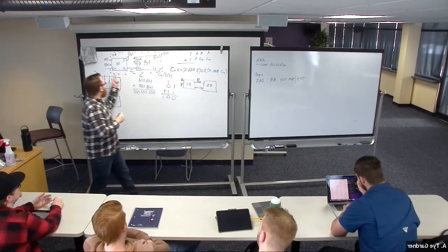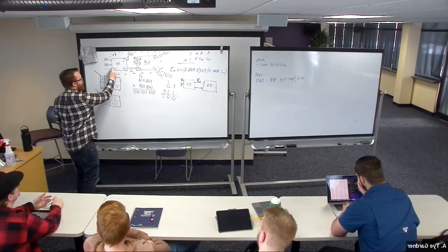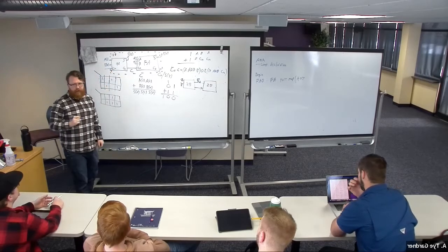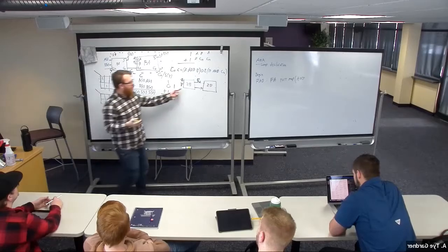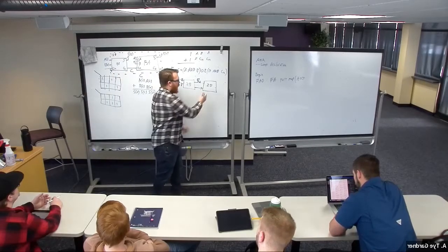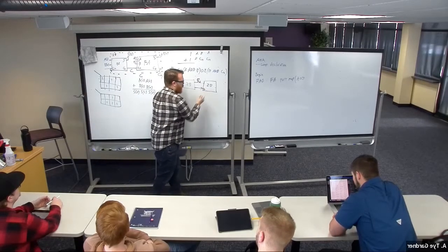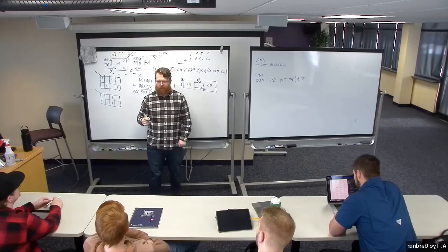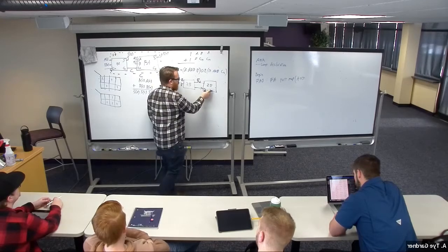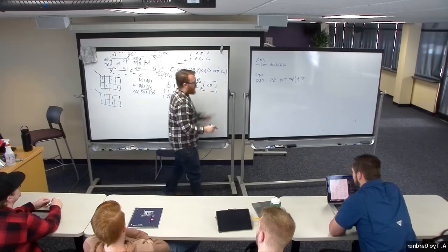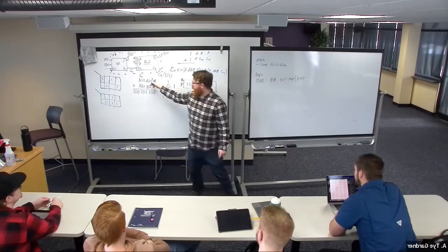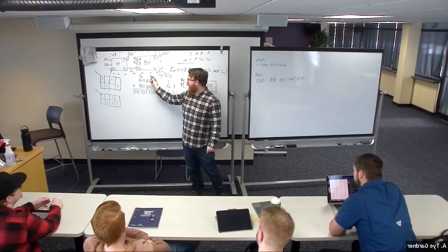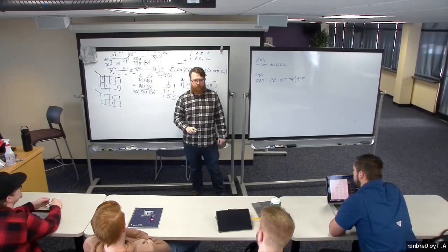If I tie it to ground inside of the component, then it can never be anything but 0, which is a problem because then when this carry in is supposed to be 1, inside it's actually tied to ground and it's stuck to 0. So we don't want to do that until the port map, right? Because I don't have a C here. There's no carry in here. This is always going to be 0.